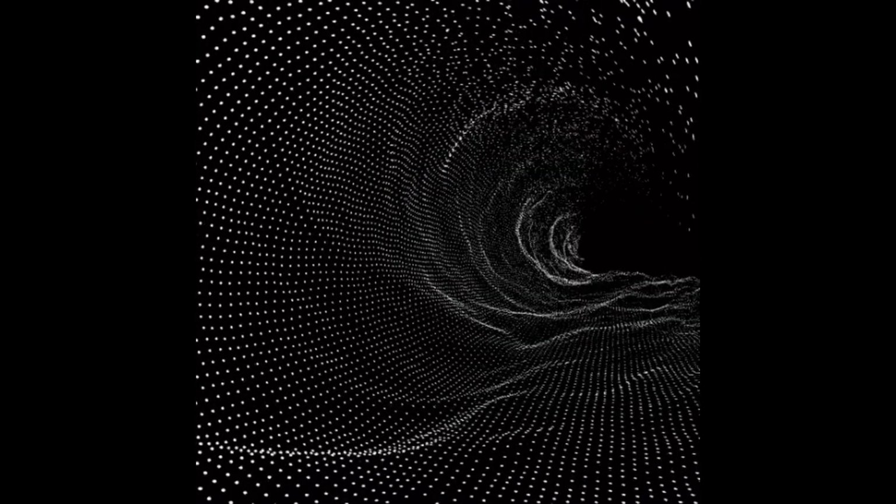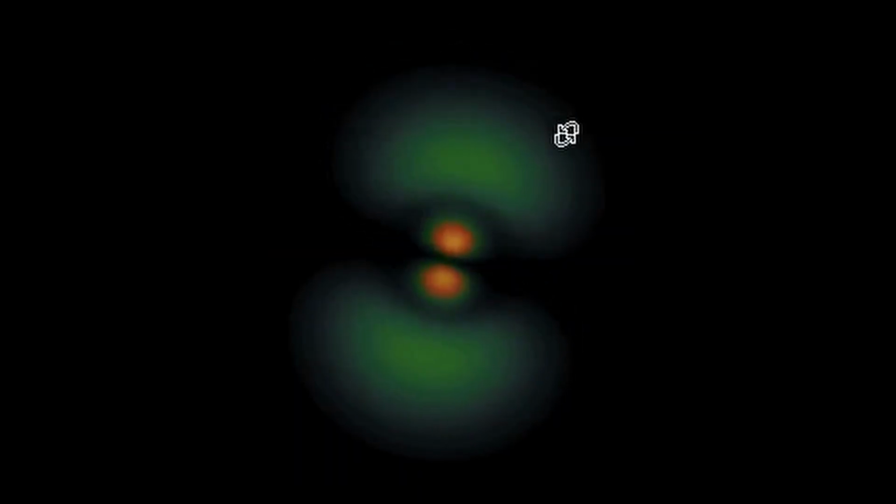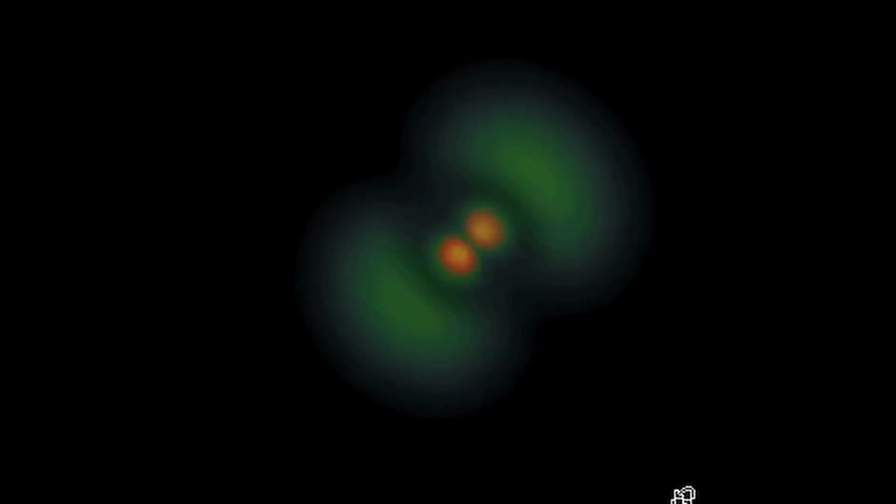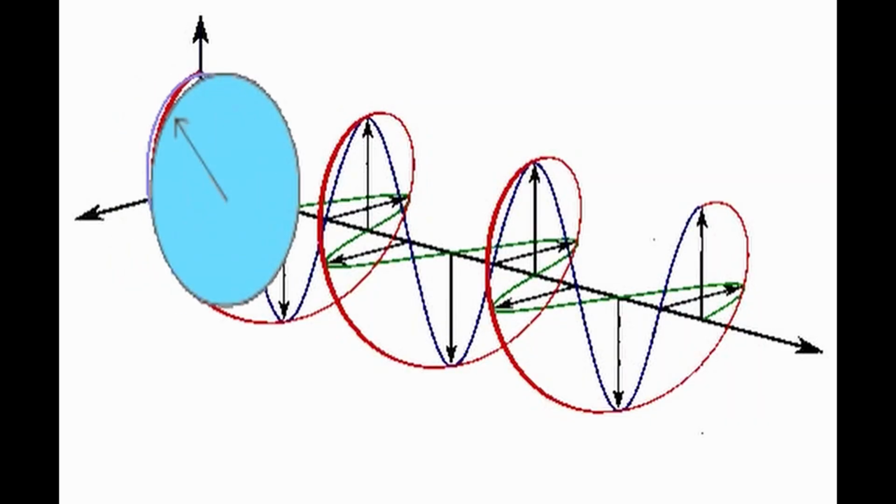magnetic flux over time. Induced EMF. The induced EMF is proportional to the rate at which the magnetic flux changes. The negative sign indicates that the direction of the induced EMF, and thus the induced current if the circuit is closed, is such that it opposes the change in flux, according to Lenz's law. Lenz's law is a part of Faraday's law and it ensures that the induced current will flow in a direction that creates a magnetic field opposing the change in the original magnetic flux.